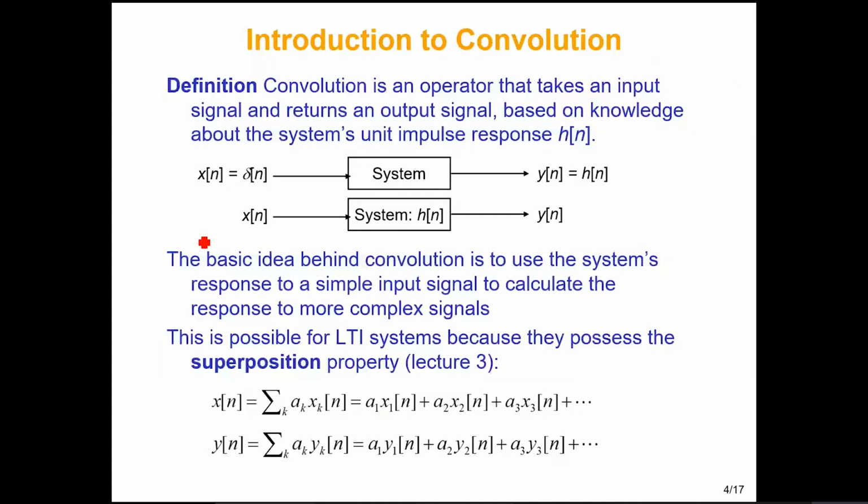So we were seeing the concept of convolution, and the first thing that I showed was what is an impulse response, h of n. The second thing I showed was that any discrete time signal can be represented as a sum of scaled delayed impulses. And based on these two, we can just build the theory of convolution, and that is what I'm building right here.